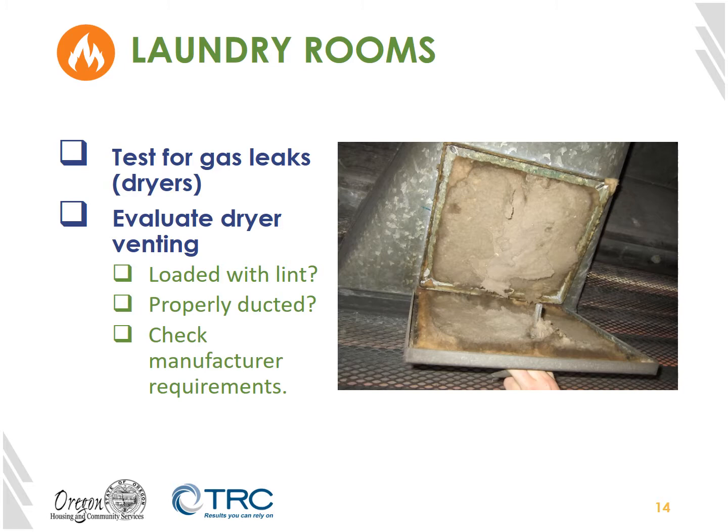Another place that we have combustion equipment may be the laundry room. If we're in a laundry room that has combustion equipment, we should be sure to test for gas leaks, usually at the dryers, and also evaluate the dryer venting. Is the venting loaded with lint? Is it properly ducted? Are the ducts crushed? Are they clogged? And we should always check manufacturer requirements to ensure that the dryers are properly vented.